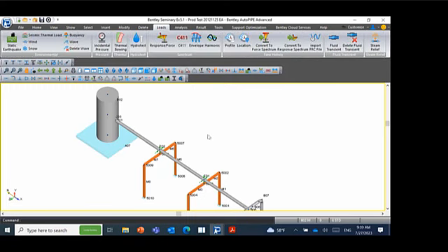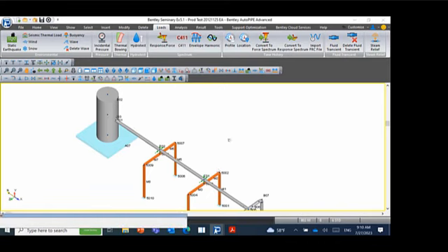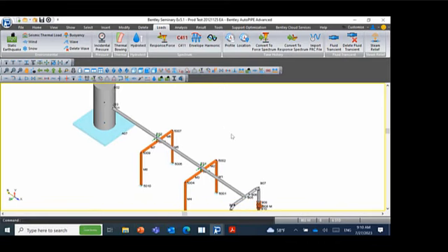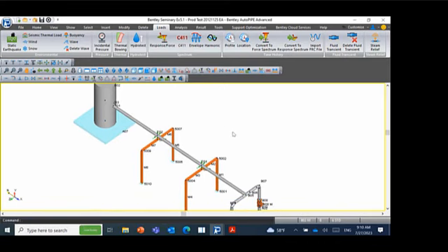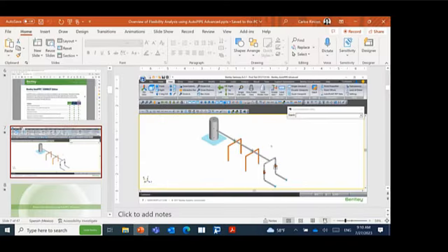You are in any system defining something, calculating something. When you want to use earthquake, you can use AutoPIPE Basic, and wind and snow. And in response spectrum, you can do it with Basic. But when you want buoyancy, wave, soil, fluid transient, or interoperability with isometric, you need AutoPIPE Advanced. Well, we return a little.